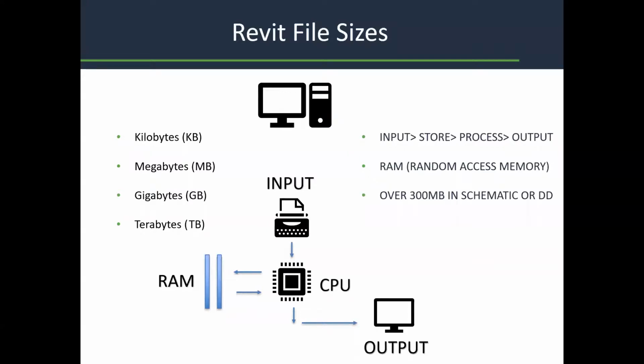So let's talk about Revit file size. We kind of talked about an overview of Dim Checker, Type Swapper, and Import and Managing Links. Removing links we'll go over in a second, but in terms of actually importing, checking where the location is, and pinning them down. With Dim Checker, we went over making sure that we were using correct dimensions in our project. And Type Swapper we used as well for swapping out text or line styles that we were using in the project, so we no longer have duplicates or ones we were never using and wanted to purge out, right?